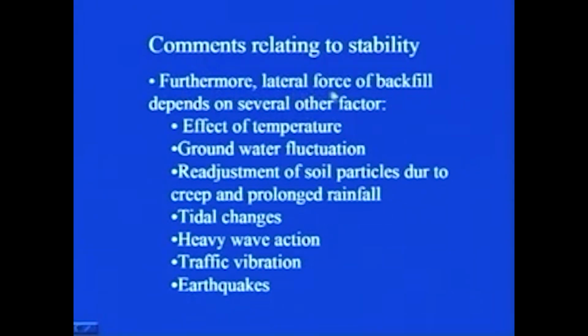Furthermore, lateral force of backfill depends on several other factors. We have simply taken the property of the backfill material into the analysis, and the property of the soil lying below the base slab. But there are some factors which we have not accounted for in the analysis, although you should have a little idea that they influence stability.